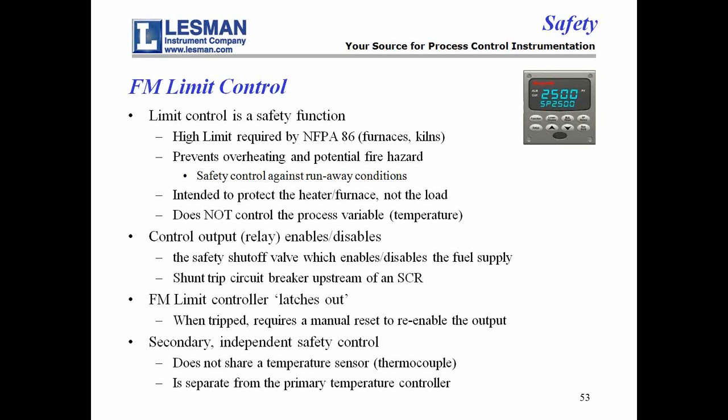It's a secondary, independent, in some fashion, a redundant safety control, but it does not share the sensor, because the sensor's got to be separate from the process control one, and it's its own separate controller. The process controller doesn't do this.